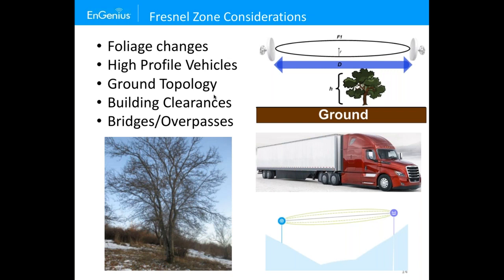So let's take one example for Fresnel zone considerations. I had a customer that was deploying a security camera and access control system at the end of a 300-foot driveway. It was in the Las Vegas area. He had large, older magnolia trees lining his driveway. And it looked nice, but the thing is that the trees were additively blocking the Fresnel zone. So one tree in itself was not enough to block it, but tree after tree after tree was enough to block it.